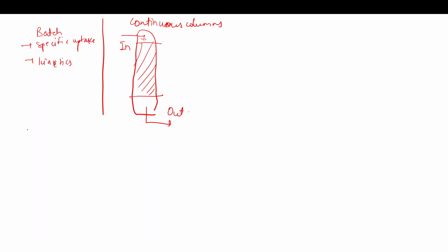So here there is one terminology which is known as mass transfer zone. So what happens is once the pollutant or wastewater comes inside the column, then depending on the concentration and obviously the length of the column, there will be a certain region where, say for example, this is the maximum concentration of C by C naught.